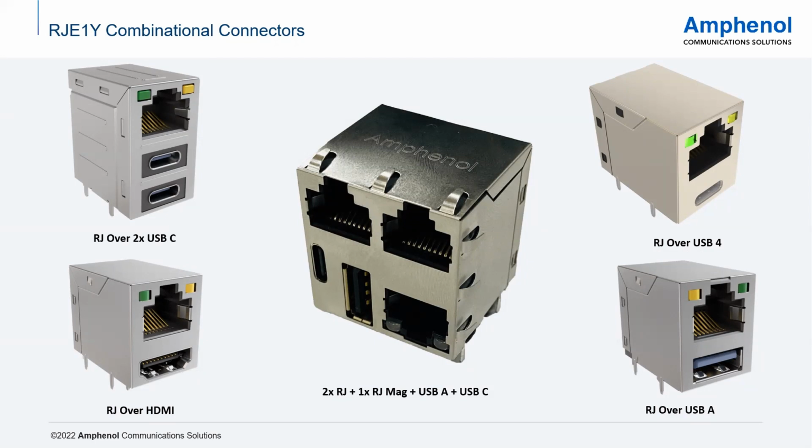Why is this 5-in-1 connector designed? The reason being for console ports or programming ports, wherein you have an application with multiple programming and storage ports, and you want to combine them all into one connector so as to save some PCB real estate, as well as some soldering. If you have 5 different products on your BOM, there'll be 5 different solderings you need to do. Here, you just need to solder one product.